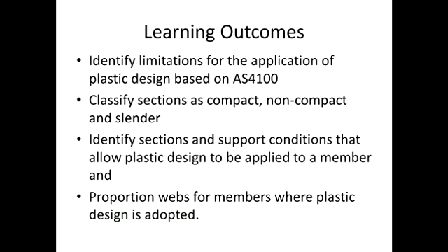So if you have a structure, then you have different members within the structure, and then if you look at the support conditions for those members, then you should be able to say whether you can apply the Australian standards using plastic design to that particular member.